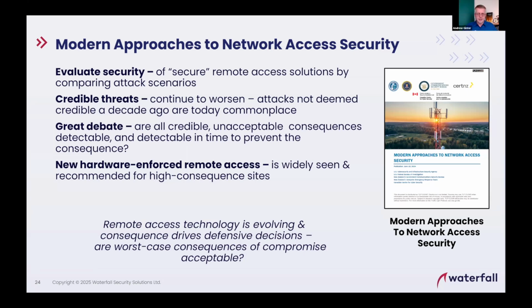So you get into a system with the cloud-based remote access. It says you're allowed to get into the engineering workstation. Now, from the engineering workstation, I try to log into the HMI, even though my zero trust OT cloud solution did not let me into the HMI. I can pivot, I can use the engineering workstation to get into the HMI. It doesn't work because I no longer know the password on the HMI machine. The password vault has changed those passwords.